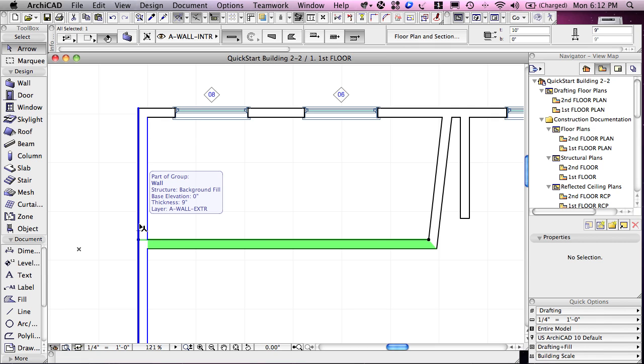Now you notice that when I highlight this wall on the left side, it has a thick line on the outside and a thinner line on the inside. Remember, I was describing the reference line, which was the line that I was drawing to define the building outline. The reference line can be top, bottom, inside, outside, but most commonly it's on the outside of a building when you're working on new construction, because that's going to be the critical or defining measurement.